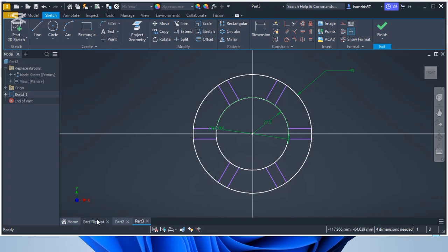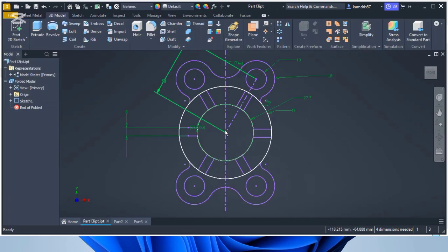But from the drawing, the distance from the center of the concentric circle to the outer circle is 60 millimeter, and it is at 60 degree from the bottom here, which is 30 degree here. So either you make this line, you bring it down to be at 30 degree to the upper line, or you rise from down here to here to be at 60 degree. So let's make it.